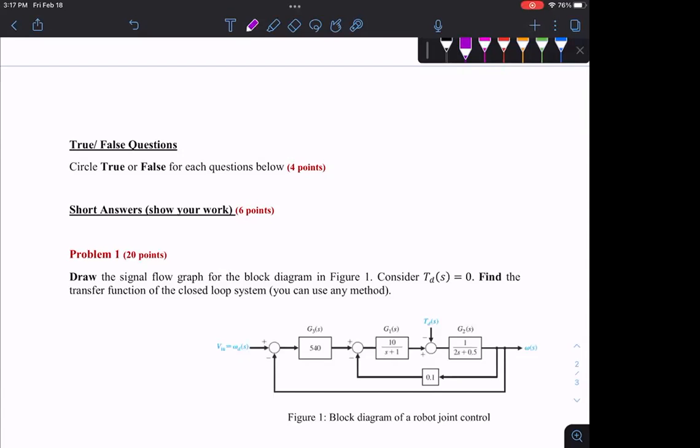You get that. Analogous system might appear in one of these 2. Final value theorem, initial value theorem, all the concepts and definitions. How to calculate pole and zero in different ways, depending on if you're in time domain or S domain, you should be able to calculate those. And writing differential equation from a transfer function or from a flow diagram.